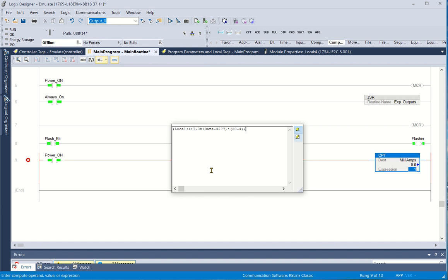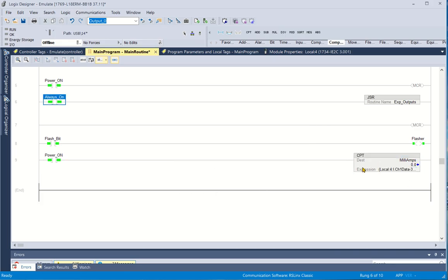And then we're going to have to divide that whole number by the whole engineering unit range, 16,383 as the high, and back to the 3277 for the low. So then we have a value, but we want it to be 4 to 20, so we have to put in the 4 to give it that offset. Okay, so it should just click out of it. It'll put it there. We can double check, verify.